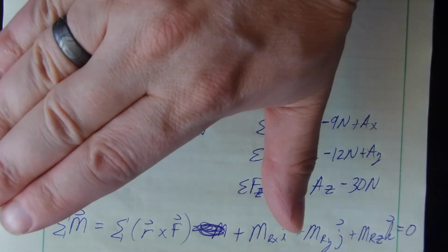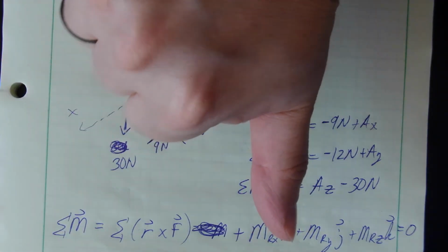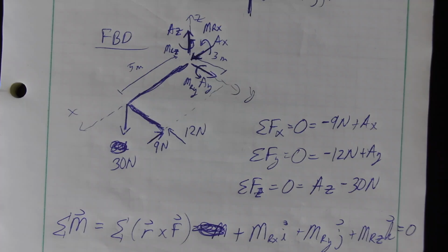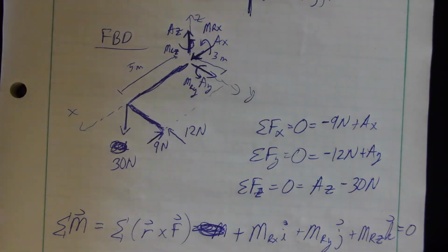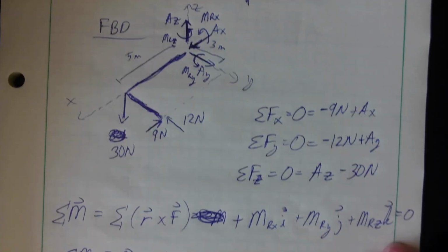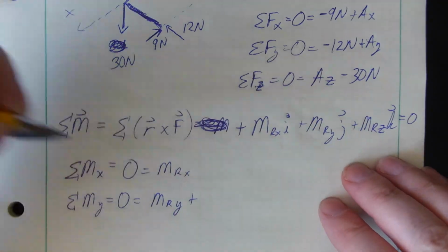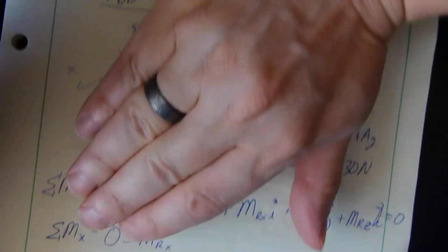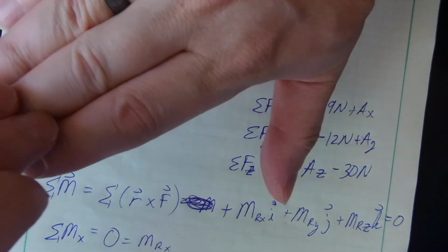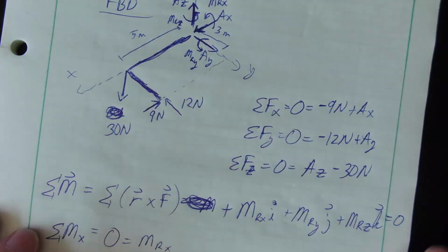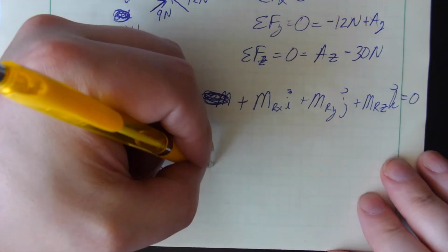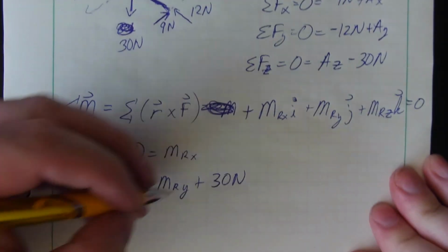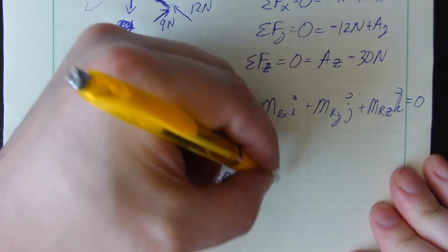Right? So notice that is causing a counterclockwise rotation when viewed from that y-axis, so to speak. So that is then causing a positive moment. Because again, thumb out here, that force is pushing 30 newtons down in the positive y direction, 30 newtons, and it is a distance of 5 meters from that y-axis.